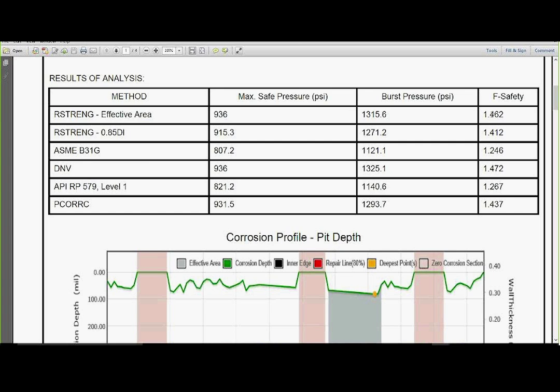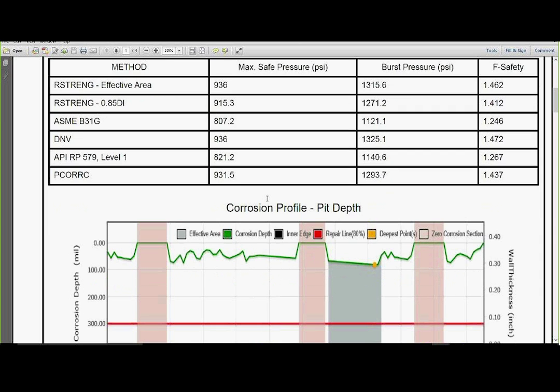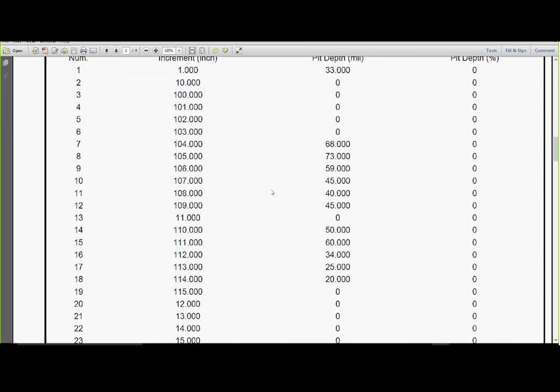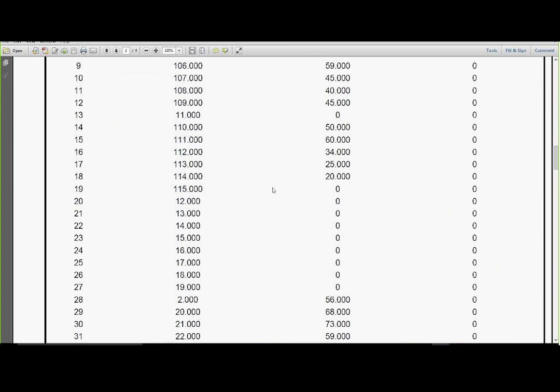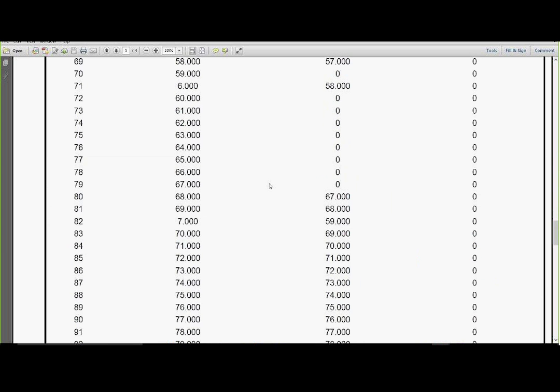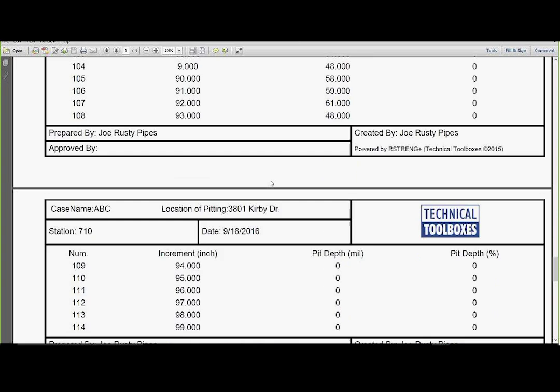If you look over here at the safety factors, a 0.72 design means you have to get above 1.39. If you take the reciprocal of 0.72, that's 1.39. And anything above 1.39 coincides with the safe pressure. And here's all the information, you know, where these composite sleeves need to go, where we zeroed out. What have we just done?